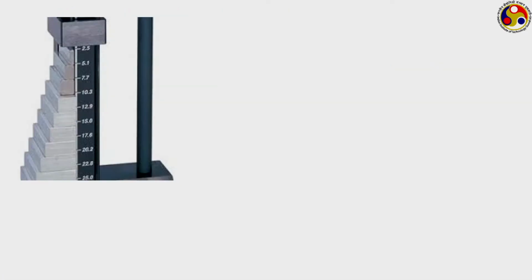And this is how gauge blocks can be stacked up. You can see there are so many gauge blocks that we have stacked up to get a final value, and once they give an exact comparison, then by adding their values we get the final reading. But the way these blocks are stacked up, that particular phenomenon is called ringing. As I have mentioned, this is one block and this is another block, and in between somewhere these blocks are joined with each other.